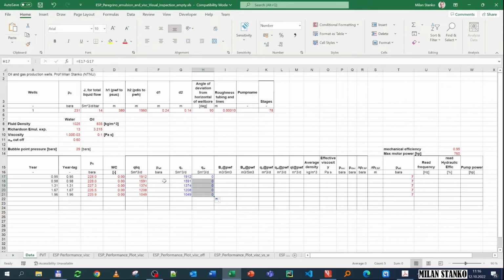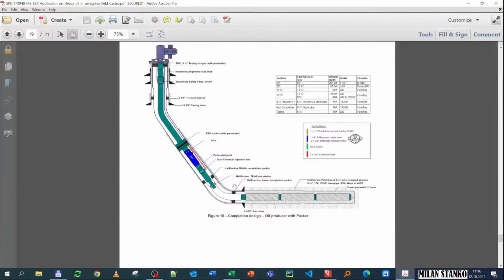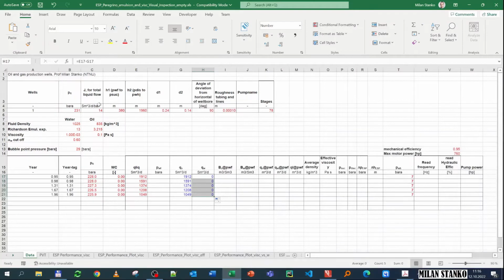Now we're going to move to make flow equilibrium. So we're going to move from the bottom hole. We have it someplace here. We're going to assume it's at the heel. Then we're going to move from here all the way to the suction of the pump. So first we have the rate, and then we want to calculate what pressure I need to apply here to get that rate. So as a bottom hole pressure, that I do with the IPR.